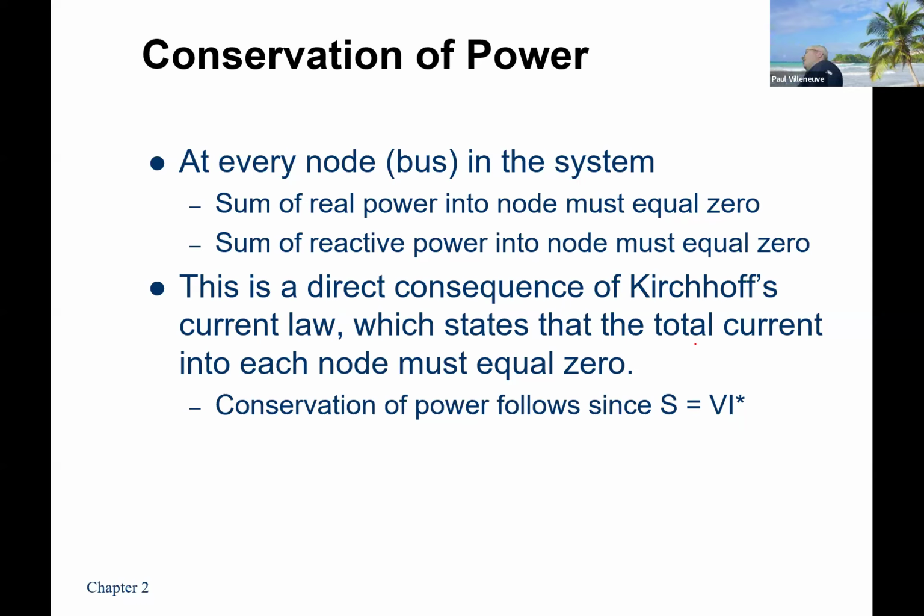But every wind turbine generator, every inverter, every hydroelectric facility, every fossil fuel, nuclear, whatever technology you have, if it's going to connect to the grid, you're going to have all this information. You look at the nameplate, it's going to have power factor, voltage, and rating, usually a watt rating or megawatt rating. Those are kind of the baseline pieces of data. You'll also have some impedance data on it too, but sometimes that can be more detailed, so usually you need a data sheet.